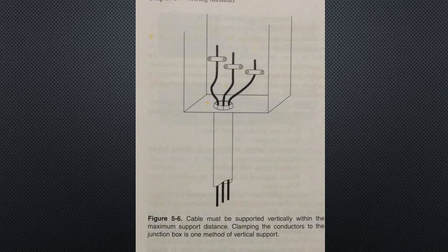Flexible metal conduit and liquid-tight flexible metal conduit are also permitted in short lengths, no more than 4 feet, to connect sensors, louvers, and other devices permitted in these plenums. For other types of air handling ducts, refer to Code section 300.22(C) and the local inspection authority, which may have special requirements applicable to the specific conditions.